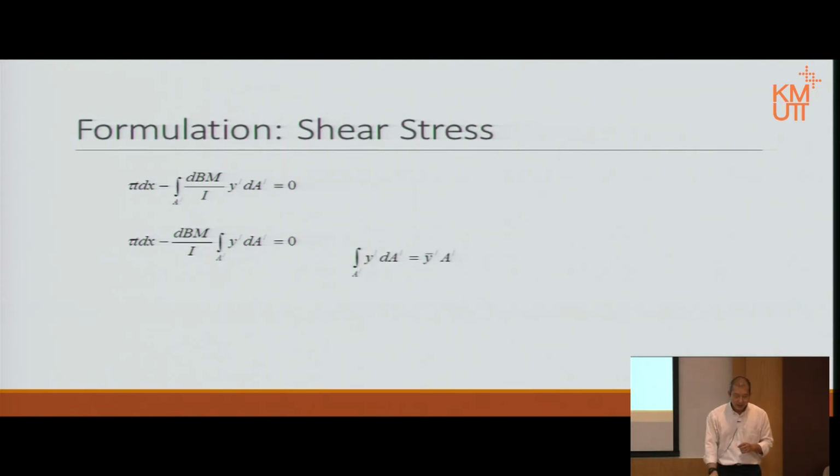Now that one there is the equation to find the centroid, correct? Therefore, once we have that integration, it is geometrical. To make it simpler, they designate that symbol, y bar prime times A prime, equal to capital Q. That Q is called the first moment of area. The area moment of inertia is the second moment, which we discussed already in statics.